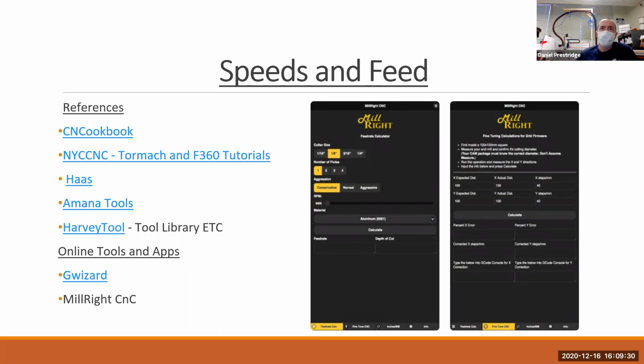And then if you can figure out what's happening and how much material you can move over a time span, called material removal rate, you can compensate too. So if you say, okay, this is going to move like this as it moves down, maybe it's undersized 4 or 5 thou every single time you cut, you can give it an offset for 4 or 5 thou, and then you can make up for those problems.